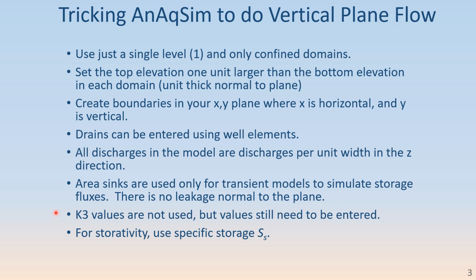The K3 values are still input with the domain input, but they aren't used, and they're irrelevant because there is no leakage or flow normal to this plane. And as I said before, for the storativity, use the specific storage, because our unit thickness is just 1, so even if we did call it storativity, it would be the same as specific storage.